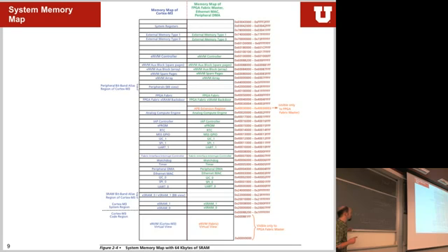So the problem is you can't just write one left shifted by 30 into this register, right? Because what would happen is you would set all these bits to 0, and that bit to 1. So you just changed the output of your I/O lines. What if you don't want to do that? Well, the first thing is you read this register out, get the status of all the different bits. Then in code, you flip this particular bit and write it back into that register. Made sense? So you read the status first, flip the bit of that status, and write it back. Then you know that these bits have not changed.